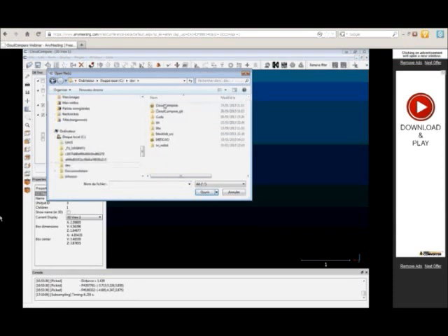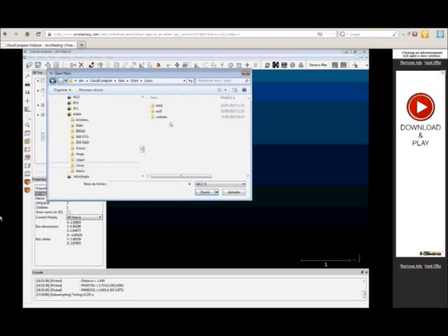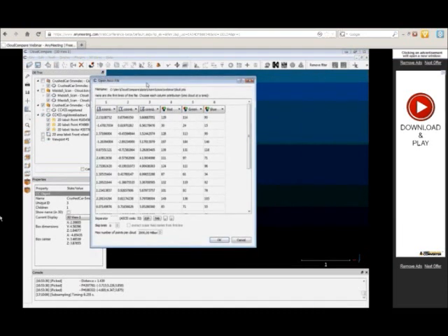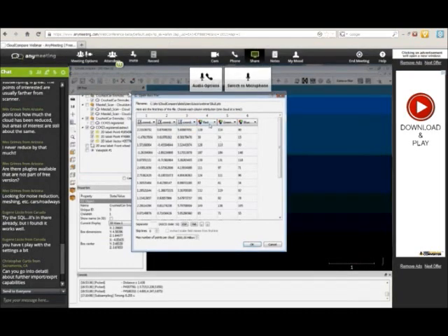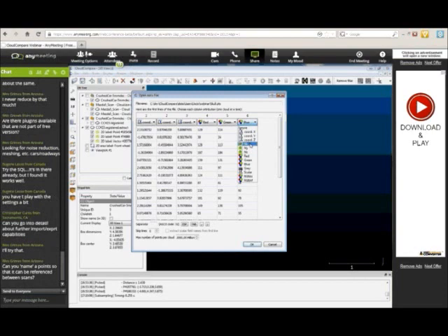So when you try to load an ASCII text point cloud like PTS, you will get this wizard, which lets you assign each column of values to a particular role, for instance X, Y, and Z coordinates, and red, green, blue. There are lots of other properties like normals, scalar fields, of course, particular colors.